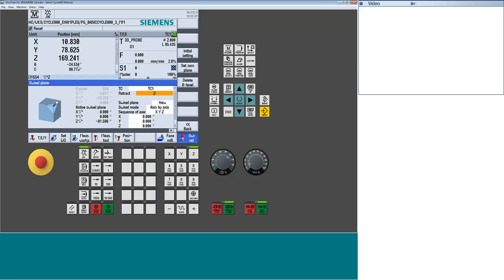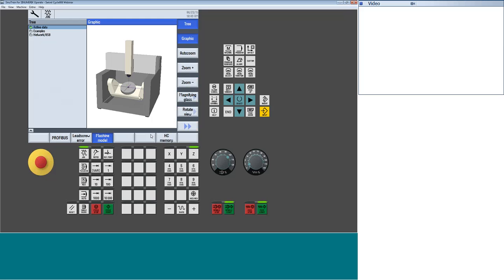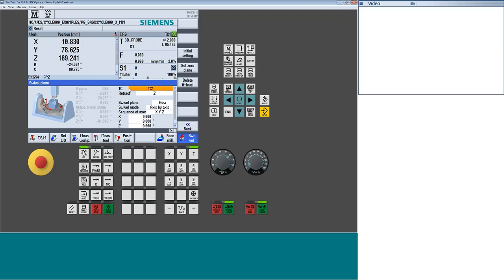The system's calculating that. What it's doing is now, if I look at the machine, she's tipped somewhere. This is now parallel. So this is the surface on my part that's now parallel to my spindle face, or perpendicular to my tool plane. So once you've aligned the plane, the next step in the system calculating where the part is, you want to align an edge. Potentially a straight edge that I'm going to touch off and establish some 0 to, may not be parallel to my x-axis or my y-axis.